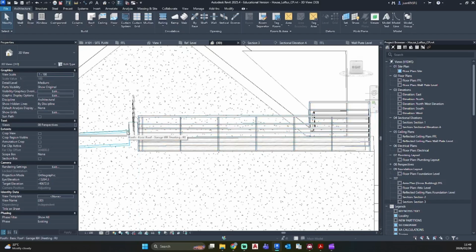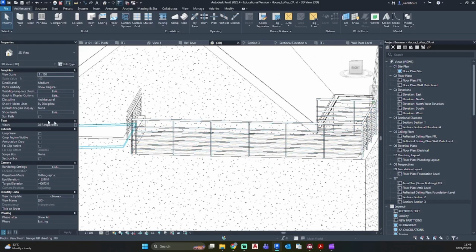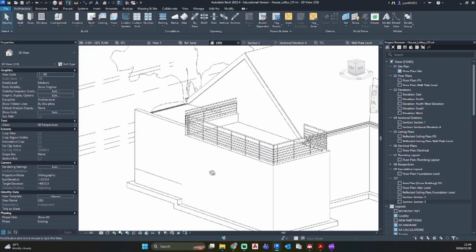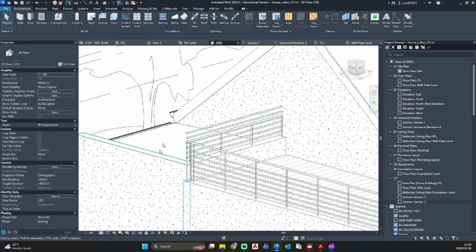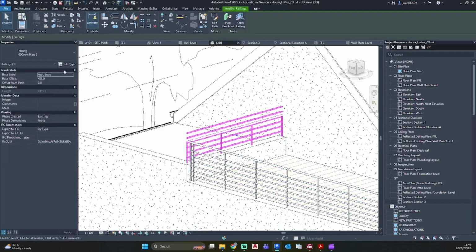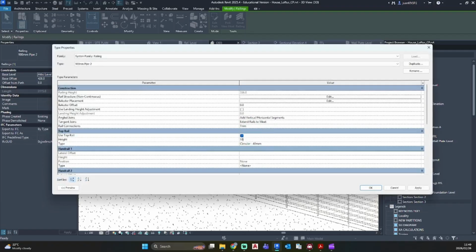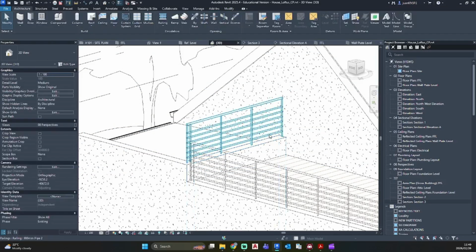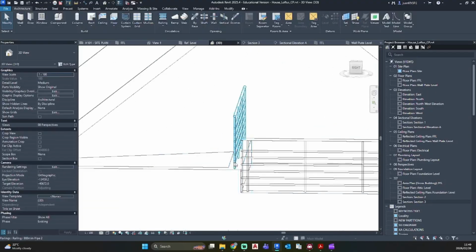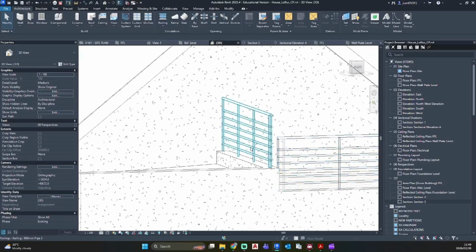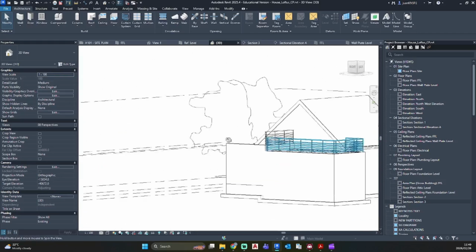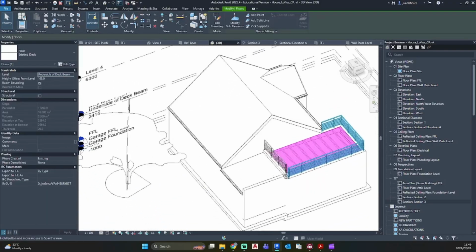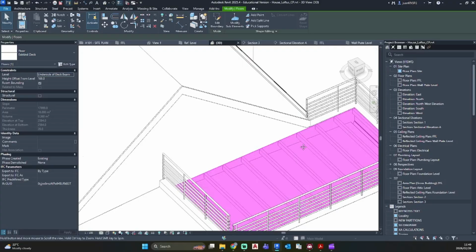But we can't drop that down due to the roof. We can't lift it up. So this is another problematic section once I am going back to site again to check what has been done on this area. So I'm just going to change this back to 1 meter for now so that we remain compliant, that no kids can climb over this section. Because if that railing is the same height as this, they can climb on top of the wall and jump over onto the roof. So there we have our deck with our garage, with our roof.